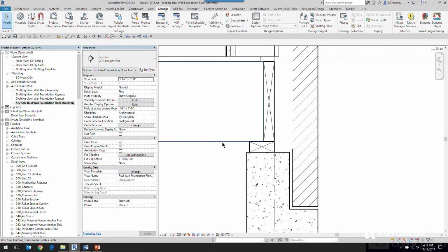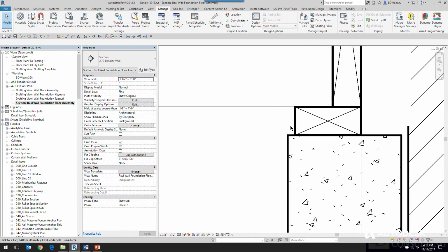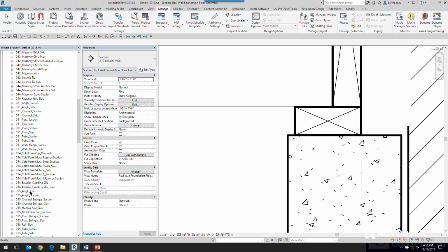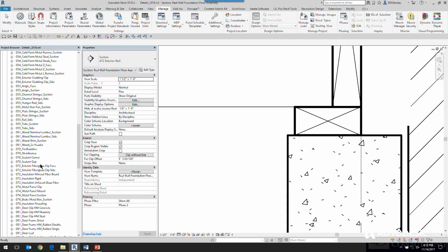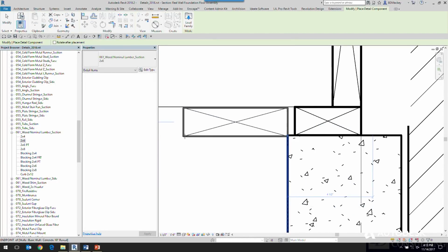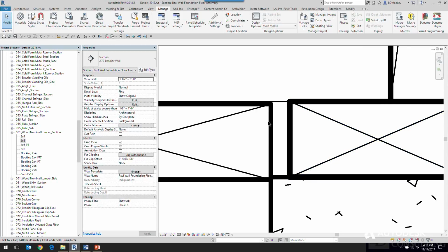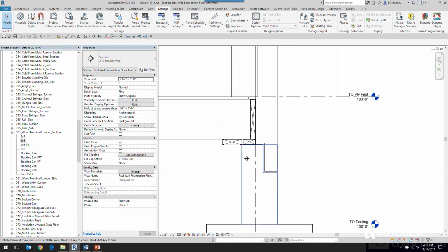But yes, the other critical thing if you are doing this is going through and verifying that your 3D model line weights match your detail item line weights. This becomes very, very critical when you're looking at it. So if I were to come down here and grab like a 2x4, 0.6, nominal cut lumber, where am I? Section. So if I come down here and put like a 2x6 down here or something, you'll notice that my line weights are the same. That's not out of the box. That does not happen. So verifying that the things that you're cutting through in your model stuff match the line weights of your 2D stuff makes this a much easier process to where people really won't know what's 3D and what's 2D. The other tip on that is, again, wait, now I got my line weights all cool.